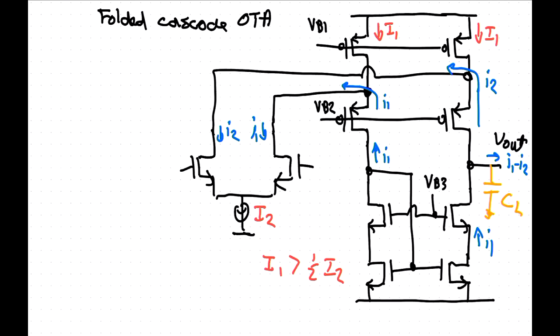So we can't put all of the current in I2. If you make I2 equal to 2 I1, then there's nothing left here. Yeah? So that won't work. Then it's not biased. And the total current here is I2 plus 4 times I2. Is that right? Well, the total current is 2 times I1. Yeah. Which at minimum is 4 times I2.